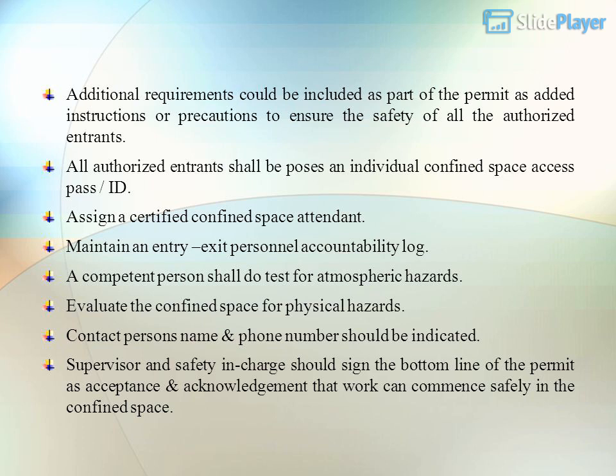All authorized entrants shall possess an individual confined space access pass, ID. Assign a certified confined space attendant. Maintain an entry-exit personnel accountability log. A competent person shall test for atmospheric hazards. Evaluate the confined space for physical hazards. Contact person's name and phone number should be indicated.